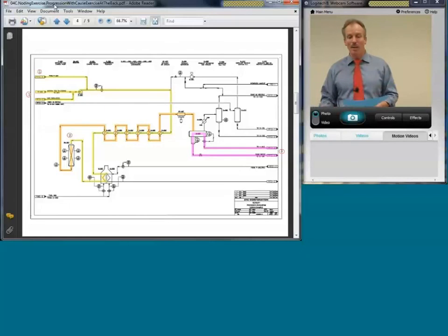That's another way to pick up time and also do a really good quality job. So if you've just finished the product separator, the next logical thing to do is the separator knockout pot, D005. That's the area that you see in blue. I would make that node 4.